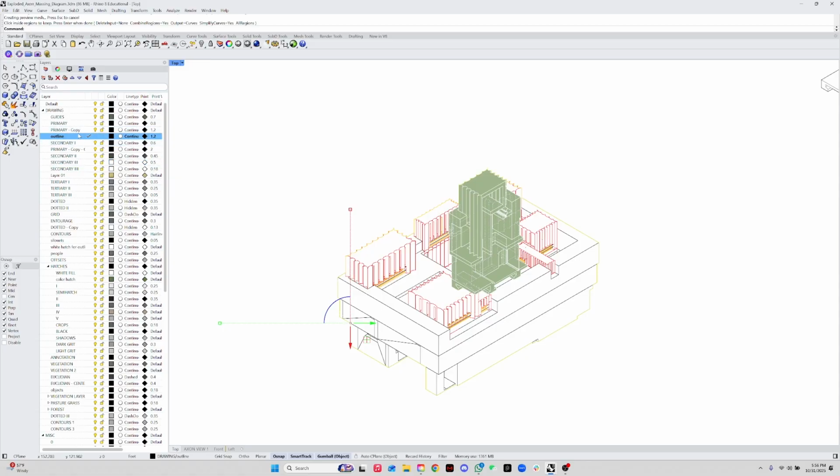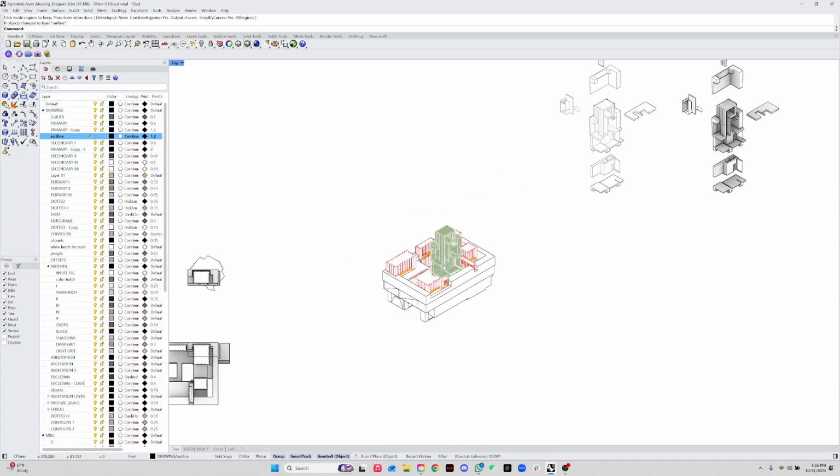And I already have an outer line layer, and I suggest that you guys create one as well. So that's gonna be your thickest line. I have it at 1.2, and I call it outline. So I'm gonna have all my outlines on that layer.